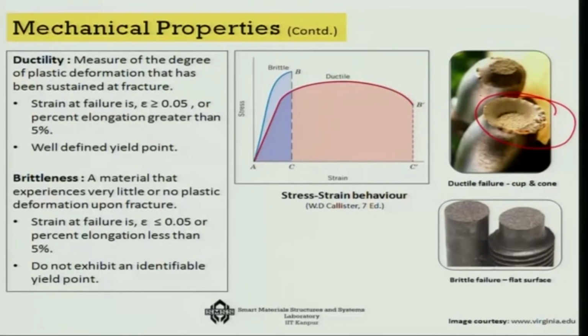So, the difference between a brittle and a ductile system, for which I have already drawn the stress strain curve, is precisely the presence of this plastic strain for a ductile material, and that is absent for a brittle material. So, that is a very important point that we have to keep in mind while comparing various material properties.